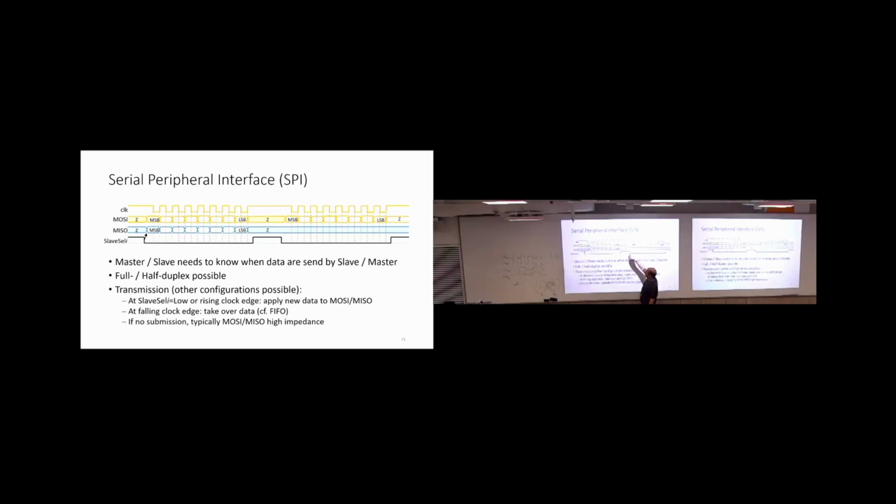Yeah? You have this enable of the slave, and then you have write data and update data and so on until everything is set. Yeah? Simple enough. Benefit, it's now synchronous. Yeah? At least in the sense that you have transferred a clock that makes it much faster because you don't have to oversample at the receiver side. And it's pretty simple to transmit. Drawback, you have more wires, a bit more logic, but overall it's, well, simple to get.